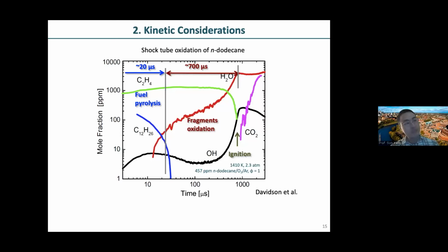So in the simulation, what we currently do is use the traditional surrogate model, and we just vary the combination of those surrogates to realize this cetane number change. I'm wondering if we want to do the same for HyChem, how to do that, because you mentioned those HyChem parameters can be linked to the cetane number. So I imagine there must be a way.